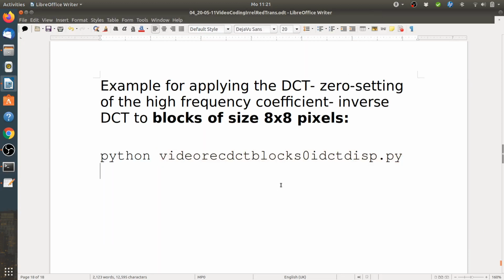So basically we have the same type of compression. We kept just 1/4 of coefficients in each dimension, which means we kept just 1/16. And we still have actually quite a decent reconstruction. I mean, it's not really great, but just for going to the 8x8 DCT and back, it's actually not too bad.